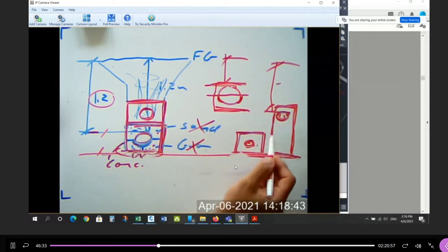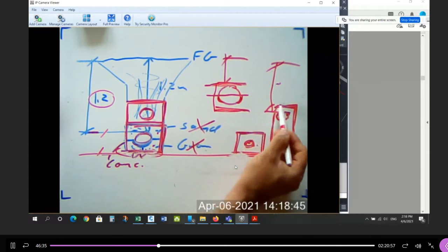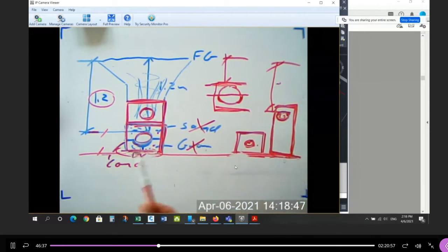So this is the trick that's played. When you have substandard cover, you regain the frost protection by making the concrete encasement deeper. Okay. Now we're not going to detail that, but that's something that's possible. As long as the pipe is underground, you can always concrete encase it.